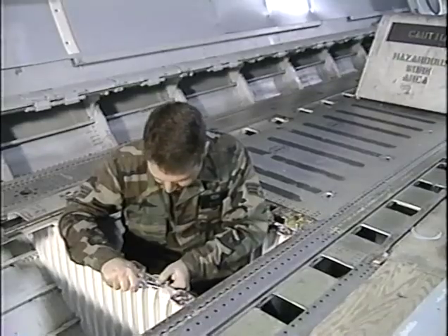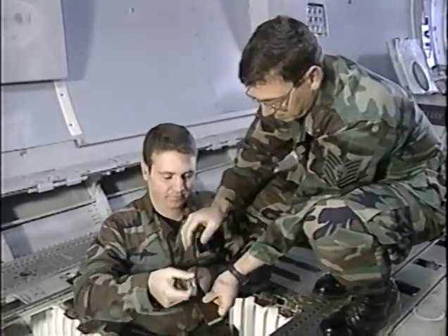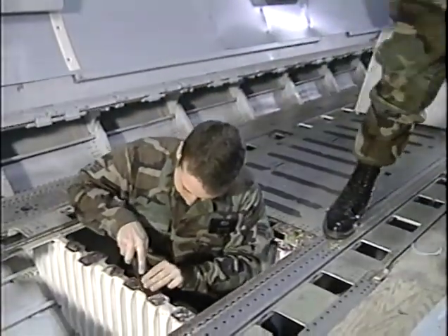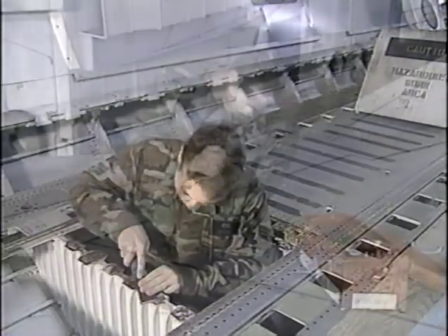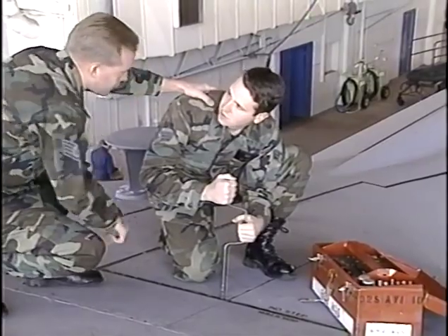As maintenance personnel, we have the most impact in the corrosion program. Proper maintenance practices and early detection of corrosion areas are key factors in combating the corrosion process. The sooner the problem is identified, the easier and less costly it will be to repair. Improper use of tools has caused a vast number of corrosion mishaps. Don't use items such as screwdrivers and knives for sealant removal. When you're walking on the top of an aircraft, do you stay within the designated walkways?